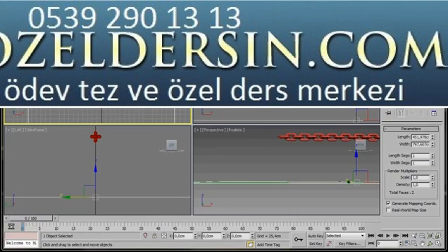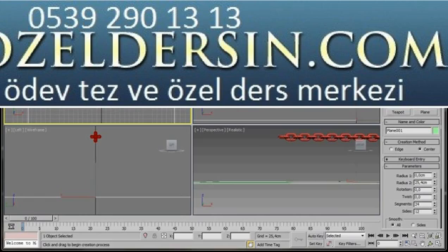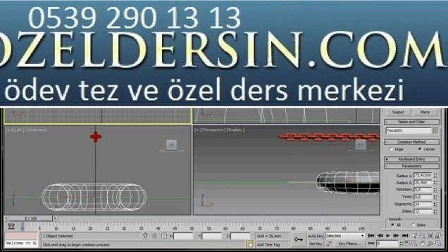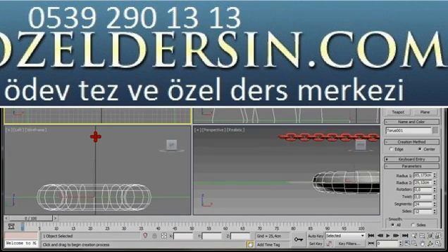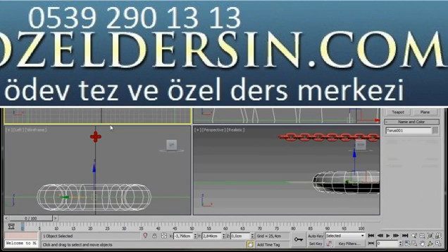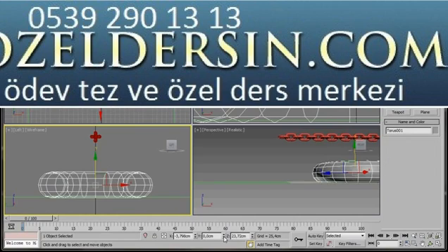Let's draw out a torus now. So I'll come back to geometry, I'll select the torus, and here in the center I'll drag out a torus. Let's create a radius 1 of about 85 and a radius 2, something like 25, something like that. And then we'll drag it up. I'll also pop down to the bottom of the panel to the transform and bring the Y and X axis back to 0, just to center it. Well, that's our scene setup.